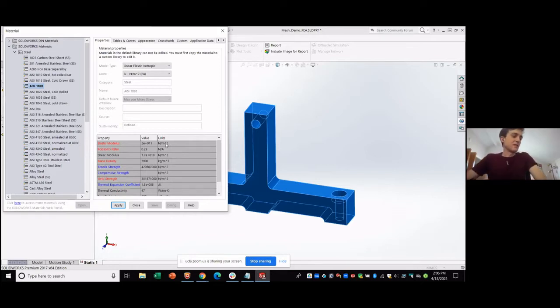What that means is that if you're simulating a material that, say, you're going to make in the context of a combat robot, say you're going to make a weapon out of some super fancy chromoly alloy that you can't get material data for, it's perfectly fine to simulate with any other grade of steel, or pretty much any other grade of carbon steel, because the elastic modulus is going to be the same.